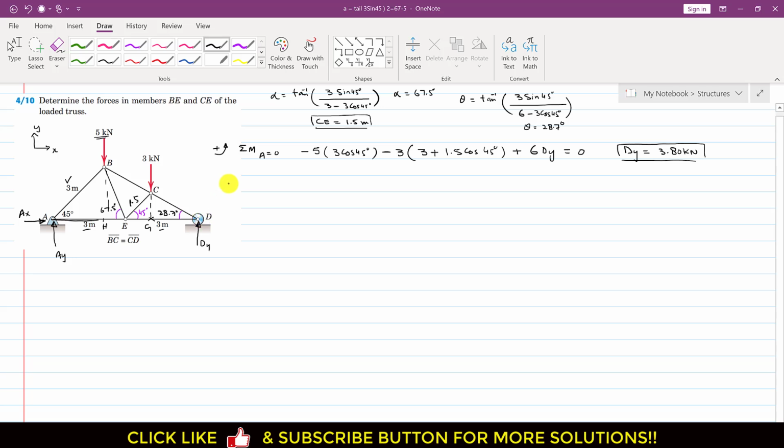Now we will start from this joint D, right? If I draw the free body diagram, let's say this is the DE force. Let me write that this is DE, and the Dy reaction is acting vertically upward, right? So this is Dy. And similarly this CD force, let's say the CD force is acting towards this joint. This is point D and this is that CD force, and as we know this angle is 28.7 degrees, right?